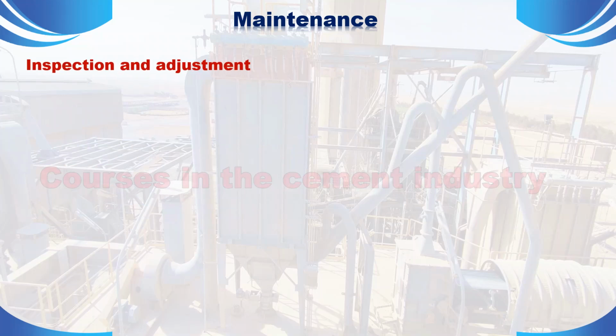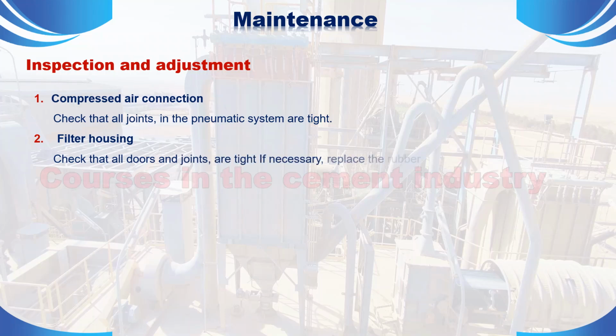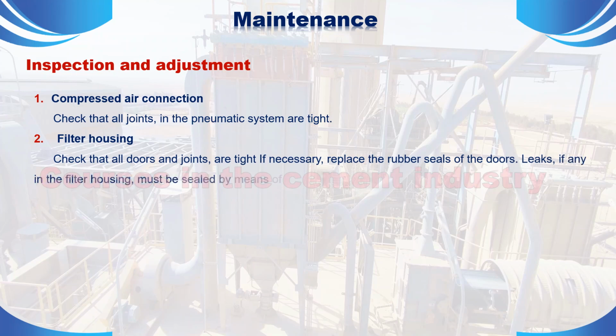Inspection and adjustment. 1. Compressed air connection. Check that all joints in the pneumatic system are tight. 2. Filter housing. Check that all doors and joints are tight. If necessary, replace the rubber seals of the doors. Leaks, if any, in the filter housing must be sealed by means of joint filler.